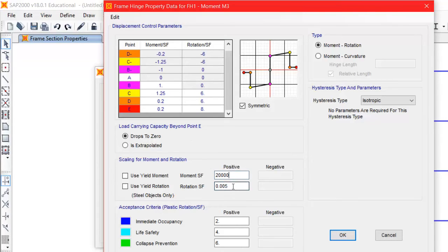Okay, so I defined those, MY and theta Y, and then I need to come here and start adding those values. In this one, I have MY, I have theta Y. So in this backbone, I'm actually modeling plastic rotation. That's why if you look here at this point, it already says the origin point 0 and 0.